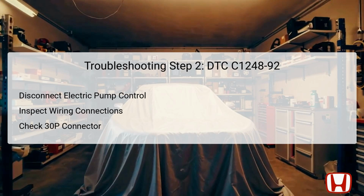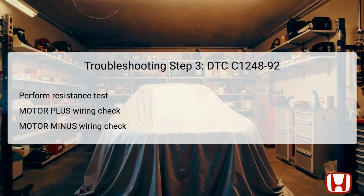that could compromise performance. The third step of troubleshooting DTC C1248-92 requires performing a resistance test on the motor plus and motor minus wiring circuits. With both the electric vacuum pump control unit and pump connectors disconnected, use a multimeter to measure resistance across each circuit. For a normal condition, there should be less than 1 ohm of resistance present, indicating that the wiring is intact and free from any breaks or opens. A higher resistance or inconsistency in readings would suggest an issue within that particular circuit.